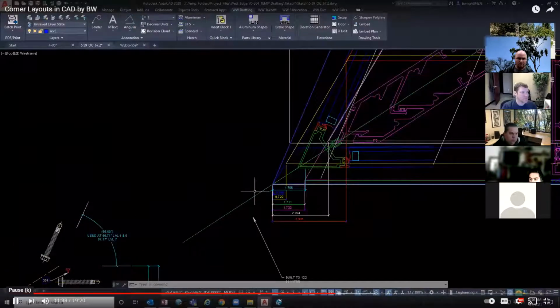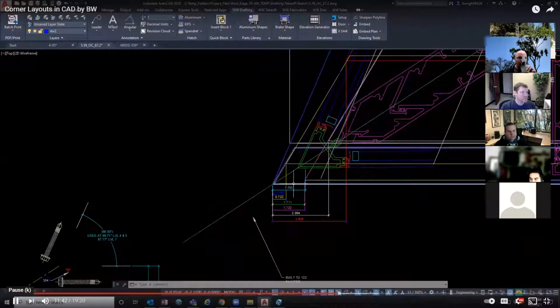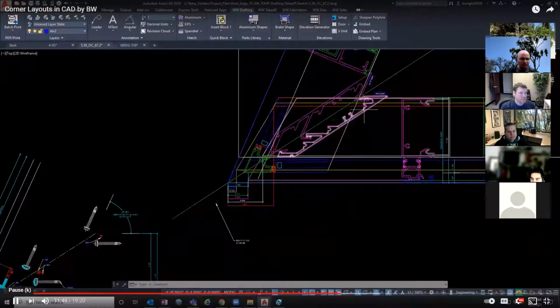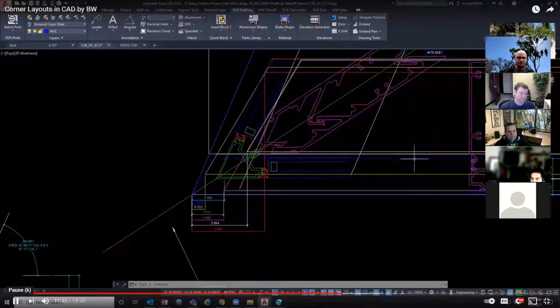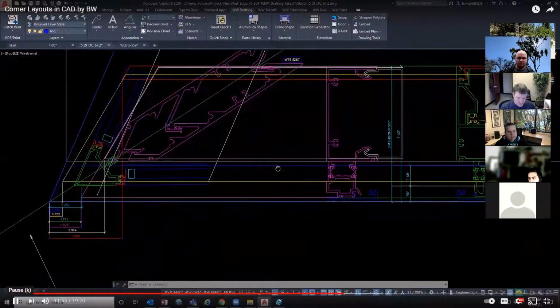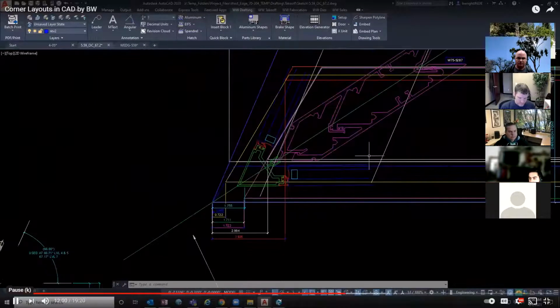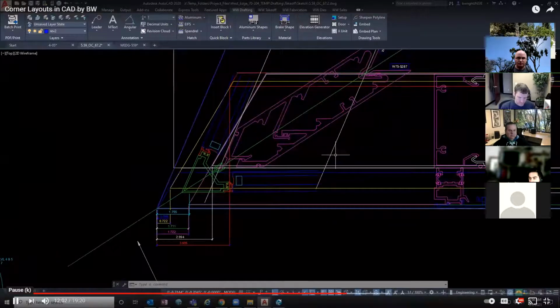From the center line, I want to do an offset of 1/32 to get the cut size for the face stop, 1/16 to get the cut size for the sill track, and then from the daylight side, I need a daylight in order to get the horizontal glass pockets aligned, and then I want an offset by 1/64 in order to get the head stop cut to size.